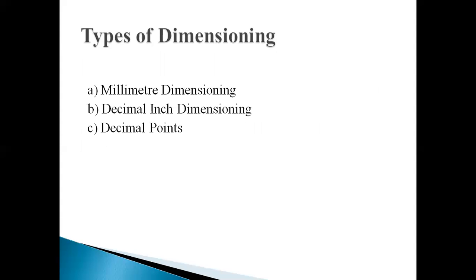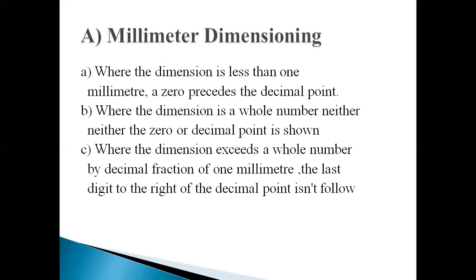Now, there are types of dimensioning: millimeter dimensioning, decimal inch dimensioning, decimal points. Decimal dimensioning shall be used on drawings except where certain commercial commodities are identified by standardized nominal size designations such as pipe and lumber sizes.